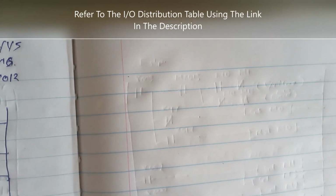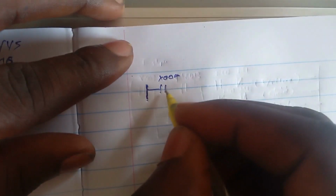Here we are in a blank page. We want to start off with our program creation. We need to first identify that we want our e-stop to be able to turn off every other aspect of the program. So from our address, our e-stop, we'll put it as a normally open contact. Let's start it off with a normally open contact X004.